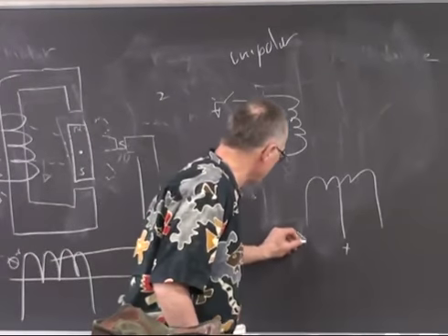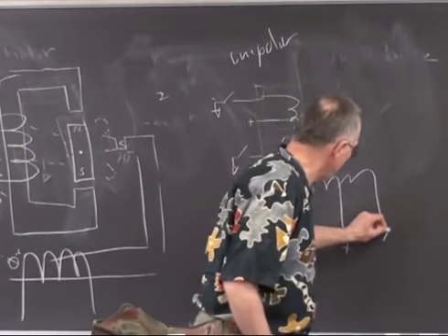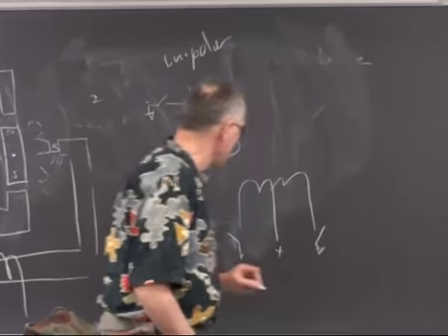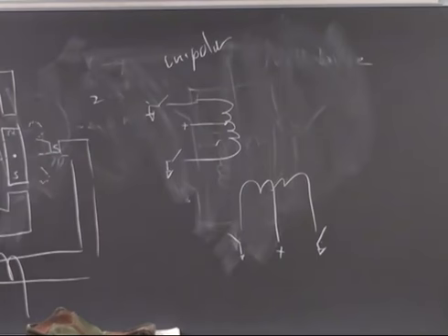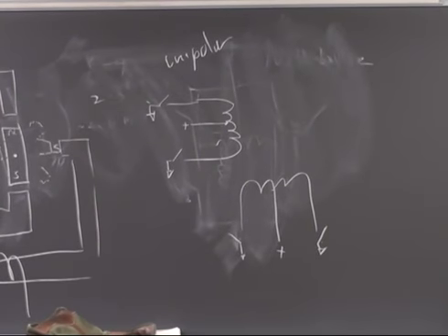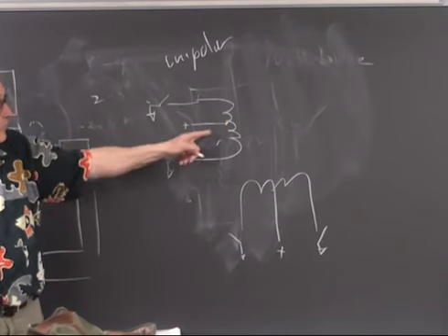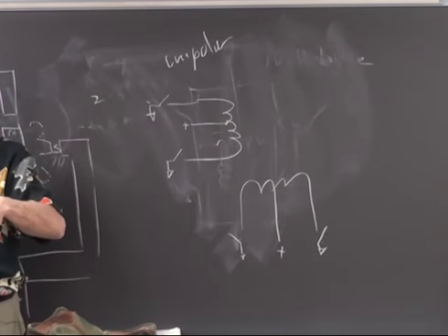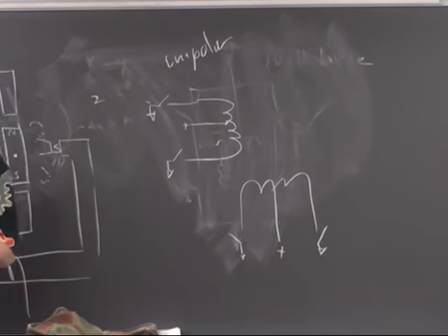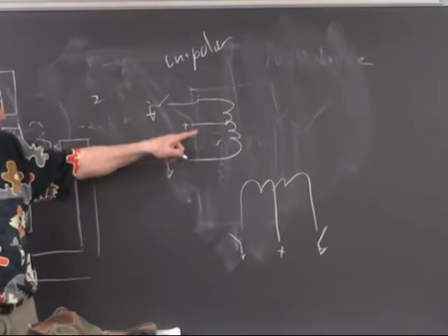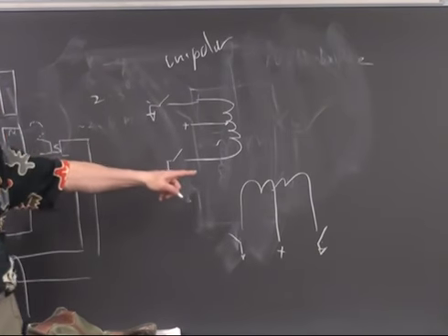Likewise here, you either ground this side or you ground this side. An 8-wire motor just splits each of these coils in half and brings out all of the possible wires. And an 8-wire motor you can either wire for unipolar or bipolar. But most motors are either 4-wire or 6-wire.